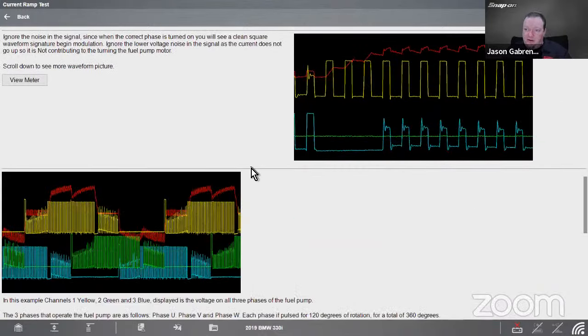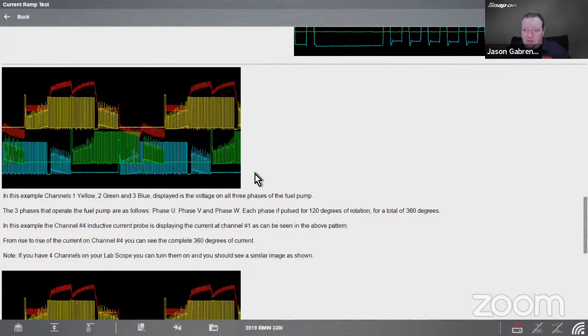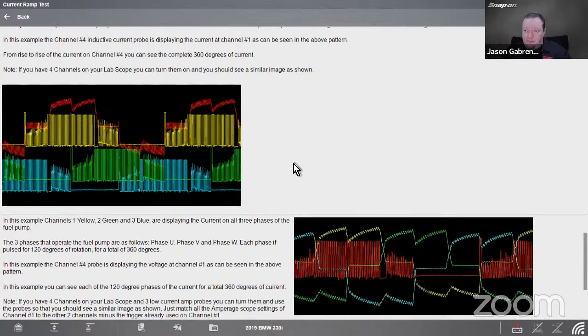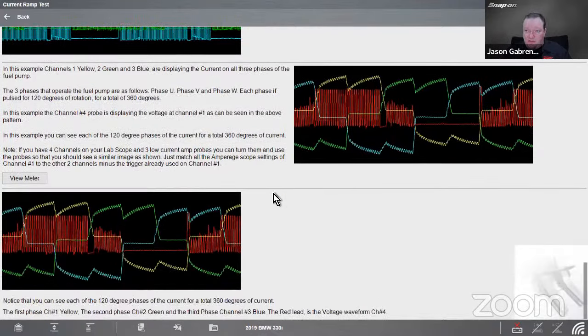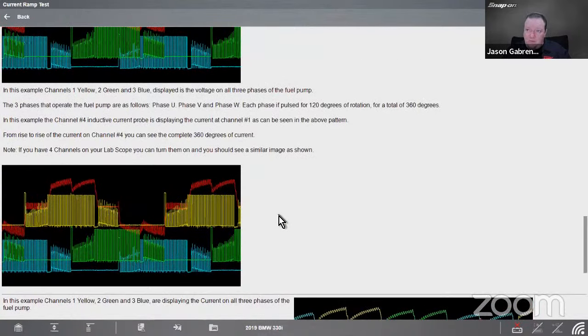That's true if it is inverted, but it is going to be inverted at some point because there is a positive side and a negative side. It switches polarity back and forth between the coils. So you'll see a positive current ramp, no current, negative current ramp, no current, positive current ramp. So you see up and down. This is a pretty good approximation of that. It looks a little different on the Toyota I was used to seeing, but you can see how that goes. You can see the different phases there and how they line up. One goes positive, one goes negative, and so on and so forth.